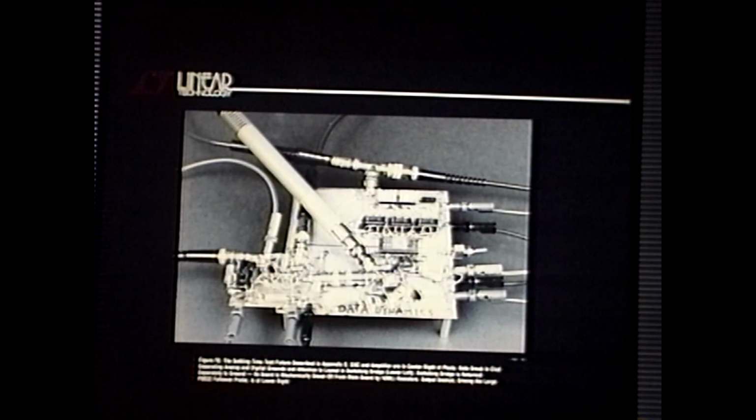Question on that. Where do you tie your analog and digital ground together? The question is, where did I tie the analog and digital ground together? Good question. Here's the 5 volt stuff here. Here's the plus minus 15. The grounds are tied together back here on the wall at the power supplies. That's where I tie them together, at the supplies.